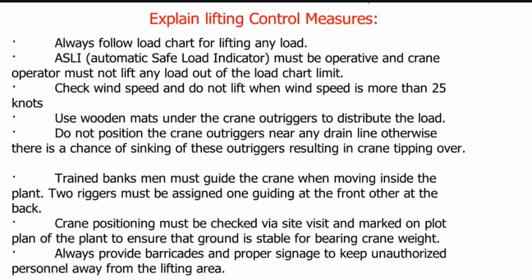Trained banksmen must guide the crane when moving inside the plant. Two riggers must be assigned, one guiding at the front, the other at the back. Crane positioning must be checked via site visit and marked on the plot plan of the plant to ensure that the ground is stable for bearing crane weight. Always provide barricades and proper signage to keep unauthorized personnel away from the lifting area.